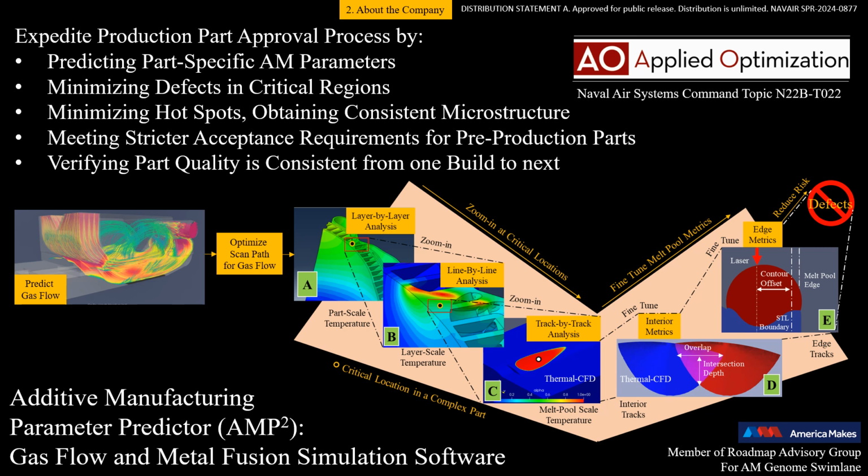These analyses systematically evolve the thermal behavior of the build and predict parameters that can eliminate defects in critical regions, eliminate hotspots, obtain consistent microstructure, and so on, enabling high-quality as-built material for the part, and consequently, higher mechanical properties.